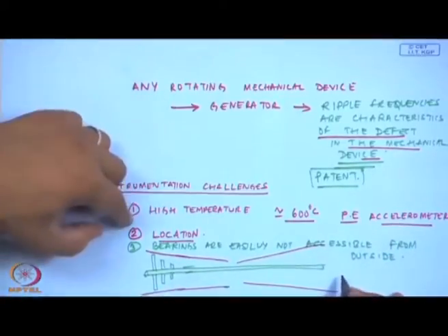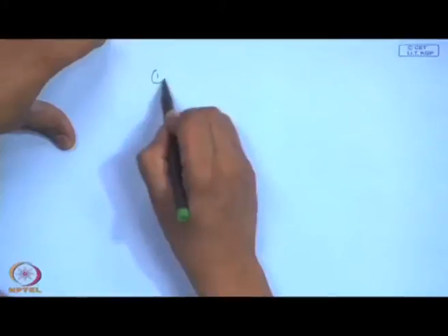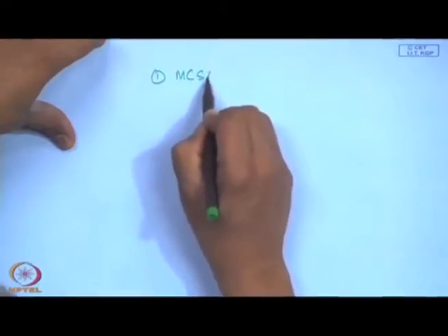So, this is again a challenge, and as you know, in all these machines the vibration reflects pretty well at the bearing locations, and if I cannot access the bearings, how do I measure them? Okay. So, that is why MCSA has become a good candidate.